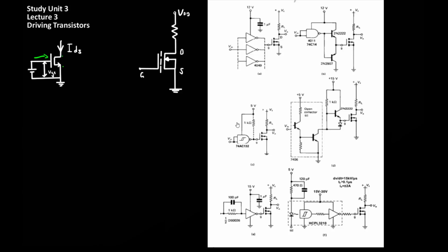The primary disadvantage with this type of configuration is that TTL logic is limited to 5 volts, so if a larger voltage is required to operate the entire switching circuit, then another solution is required. The voltage limitation can be overcome by making use of an additional external circuit which will effectively shift the driving voltage to whatever the desired voltage is. So in this example, the TTL output of the logic gate has a 5 volt limitation, but with the addition of this emitter follower BJT over here, the output level can be lifted up to 15 volts.